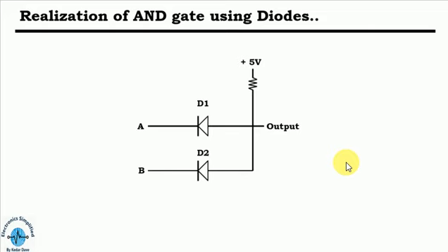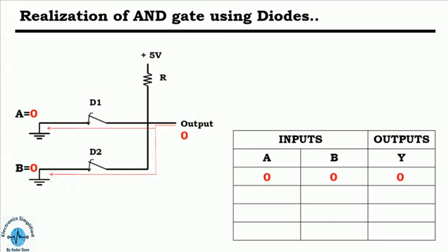So from the very first case of the AND gate, we are using two different diodes, and we are providing 0 voltage levels, means the switch is earthed right now. You can see that both the 0s are provided over here and the output is 0 for this case. Why?